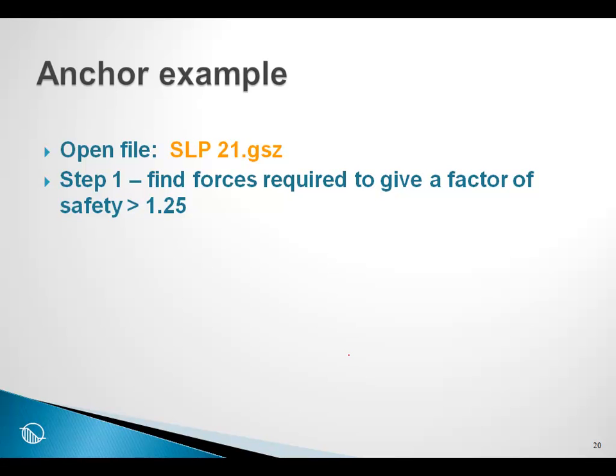Let us go then to GeoStudio and open up SLP 21. Sorry, this should be SLP 23. And we're going to begin by asking the question, what force do I need out of my anchors in order to get a design factor of safety of 1.25?